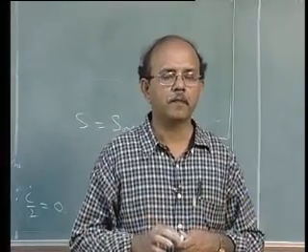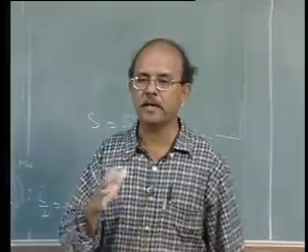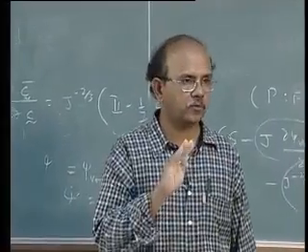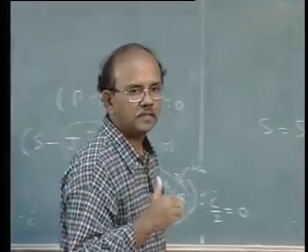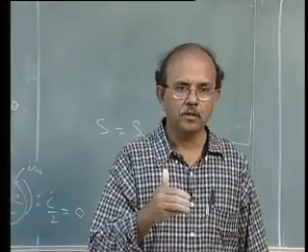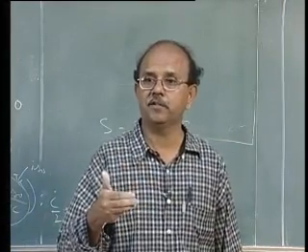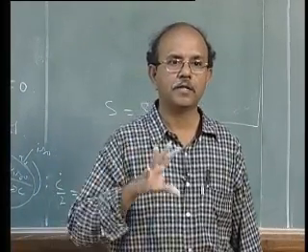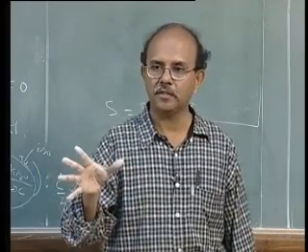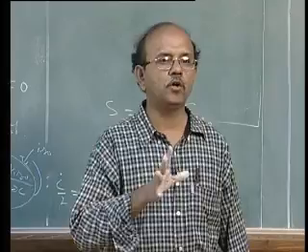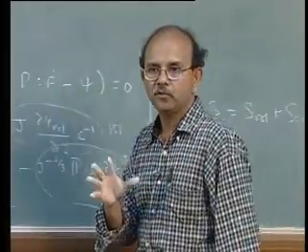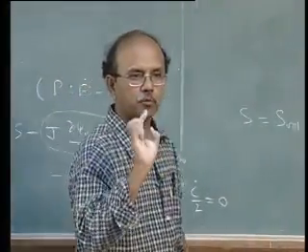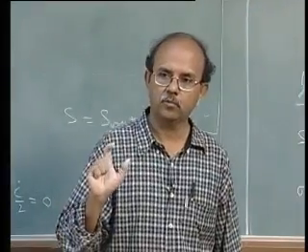What we did, the first thing we did, was to write down the Clausius-Duhem inequality. Remember that we did the Clausius-Duhem inequality first. We finished that and then came to the constitutive equation. In the constitutive equation, we defined an elastic material as one where there is no dissipation. So that right-hand side inequality sign becomes an equality sign. So we wrote down the expression for P to be just dou psi by dou F. That's concept number 2.